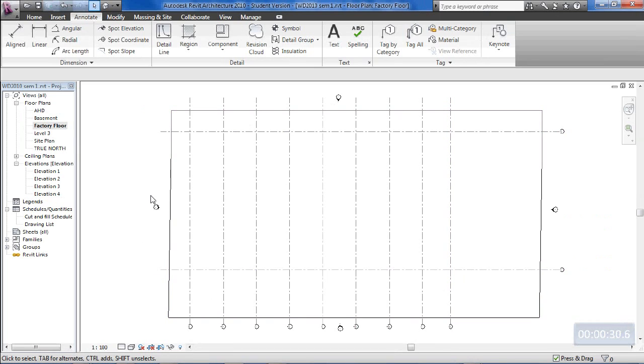That would be the one we call mass. I want to create it as a mass. Now the reason for creating anything as a mass in SketchUp is because you're then going to use it as a guide and create walls by clicking on the faces of your mass. You'll soon see how that applies as we go on.